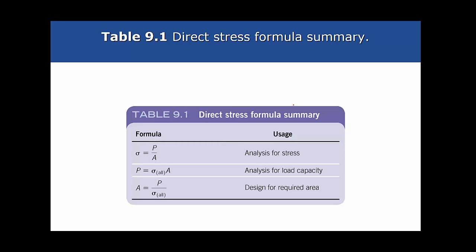There's that table I was talking about. All they're doing here is rearranging the formula. The formula for stress is stress equals the force over the area. It's that simple. Don't make it hard. So if you know what the force is and what the cross-sectional area of the piece is, then you can find out what the stress is. Stress is signified here by this sigma. Okay.